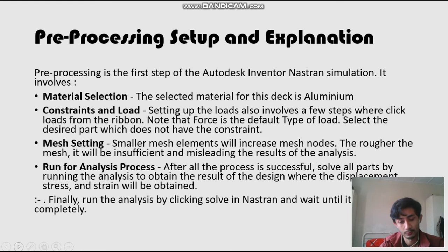After all the processes are successful, solve all the parts by running the analysis to obtain the result of the design, where the displacement, stress and strain will be obtained. And finally, run the analysis by clicking solve and wait until it completes.